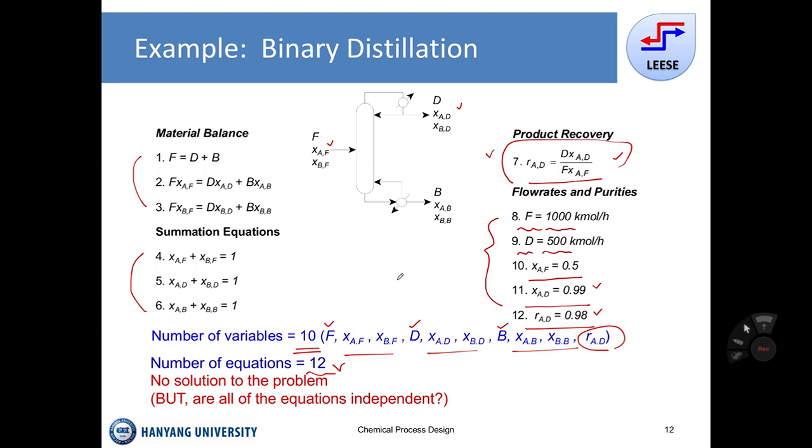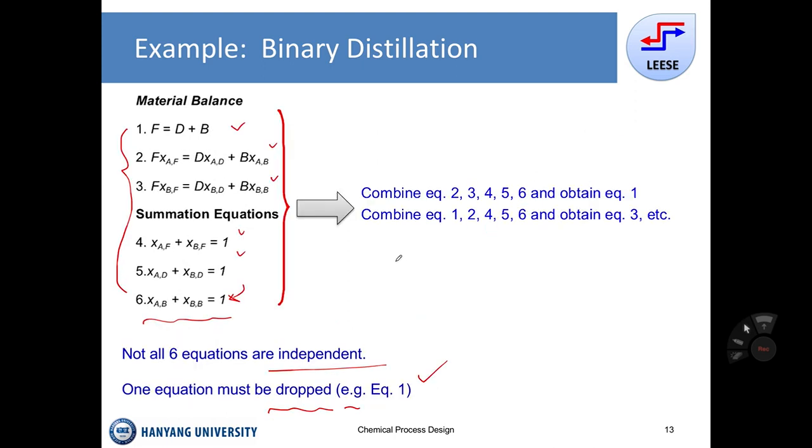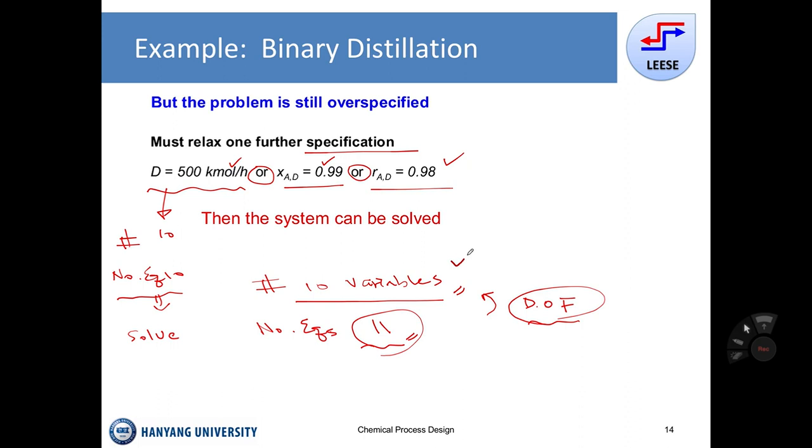So we're looking at this simple example as an illustration of how the model can be set up, how the model can be relaxed, or how we need to add more input in order to complete the unit operation model, okay? Based on the number of equations and number of variables, we may add more input to the process. For this case, we needed to take out one of the equations in order to have 0 degrees of freedom, okay?